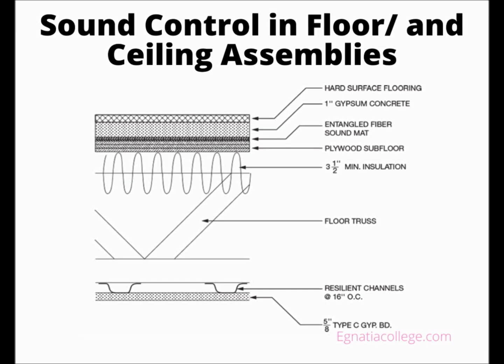Another type of sound comes into play for floor and ceiling assemblies. When a person wearing hard-soled shoes walks across a wood floor, the sound created by the impact of the footsteps can be a real annoyance to those living in the rooms below. The acoustics industry has devised a system for impact noise insulation. The Impact Isolation Class, IIC, is a rating of the floor and ceiling assembly's ability to isolate the sound from footfall and other impact sources.